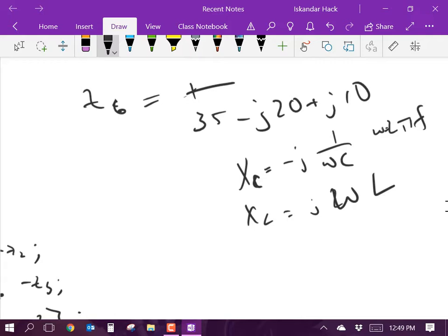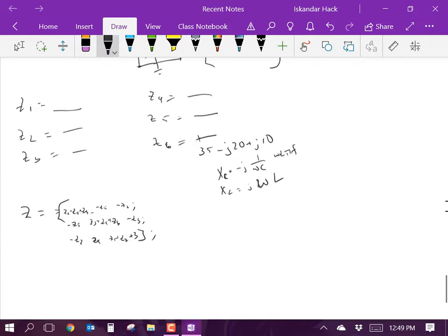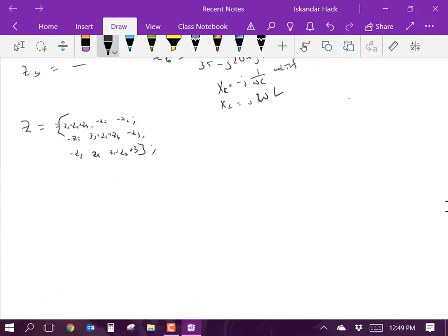First off, I'll give impedances, then I'm going to put capacitors and inductors and specify a frequency. Now you can only solve this with one frequency. You could do this in a way where at the top, and I'll talk about this later, you said f is equal to 50, and then you said w is equal to 2 times pi times f.